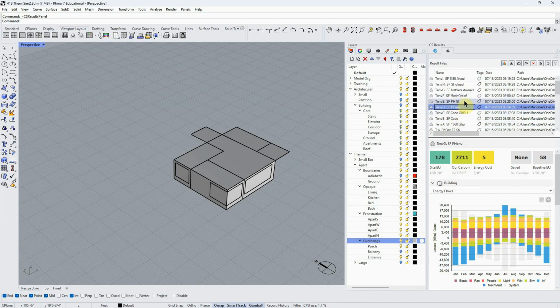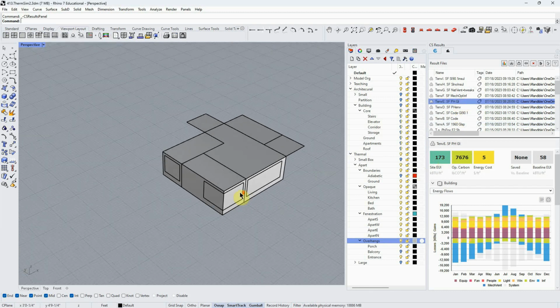Then next, I changed to triple pane glazing, improved the glazing. And again, I'm going up incrementally. These are pretty major amounts of improvement, but this is a 1,100 square foot building. So dropping your site EUI by 5 kBtu per square foot is a lot.